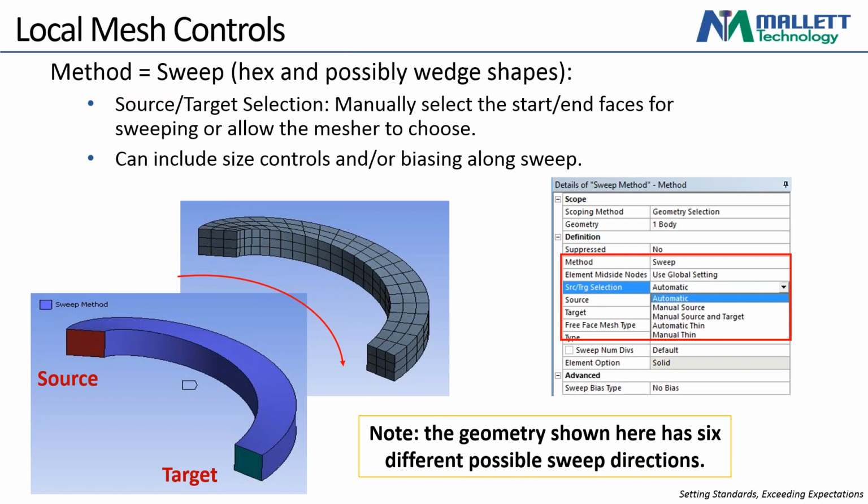Okay, so swept meshing. There are a number of different ways to sweep mesh. Essentially, what a swept mesh does is it looks at a face. In this case, in the bottom left, the red face is a source, and it says, okay, can I take this face, mesh the face, and then project that around the entire body? Here you can see it has continuous curves. This would be very similar to a not too complicated loft operation in CAD.